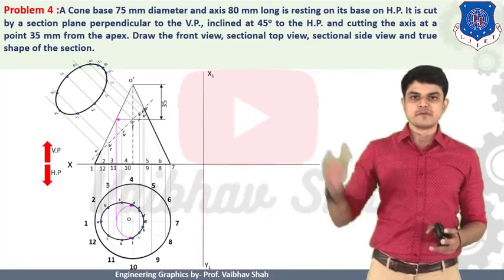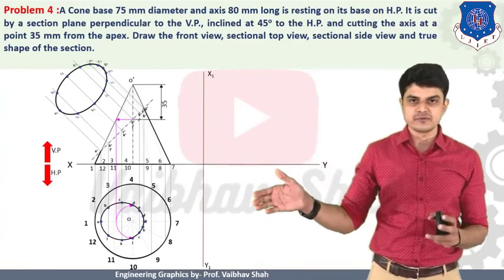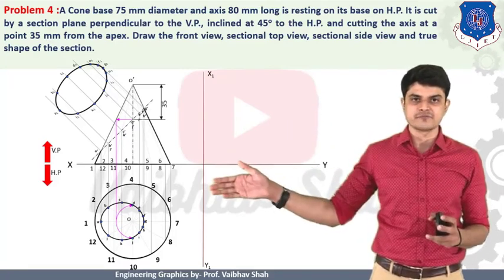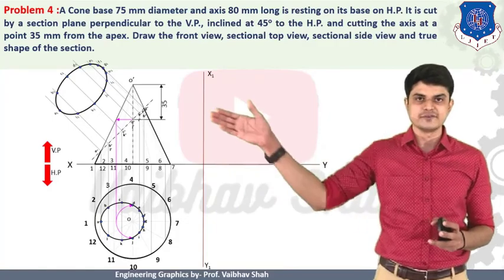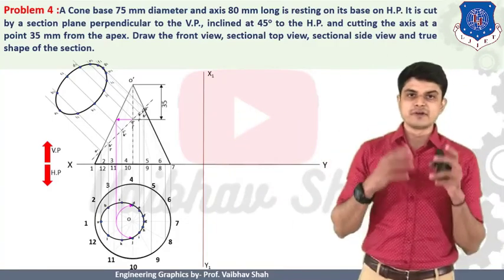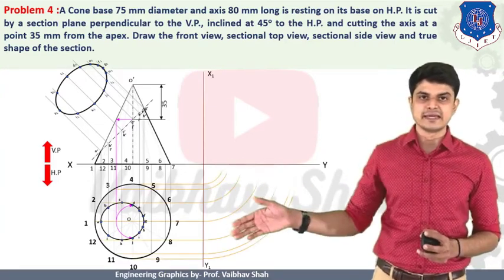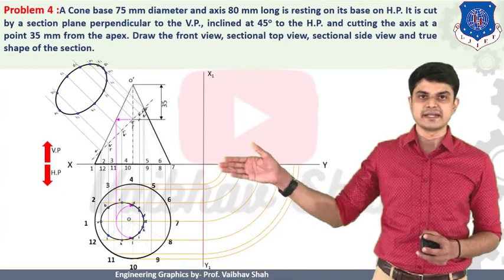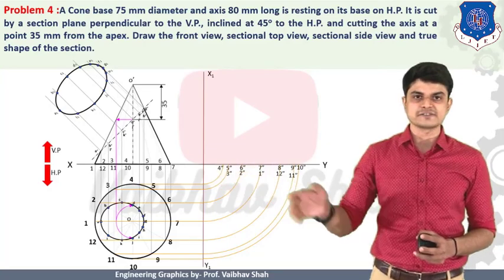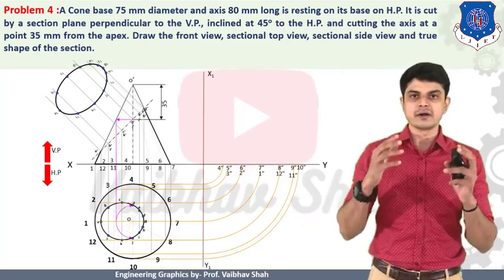Then you should draw the vertical line in order to get your side view. So this is your vertical line x1, y1, and on the right hand side this will be your profile plane. So let us transfer each and every point from your circle onto the right hand side, and we should be transferring your points horizontally in order to have the side view. So now what we should do? You should transfer each and every point on the right hand side onto your x1, y1 line, and you should be transferring each and every point by taking your radius from the center point. So you will be having each of the points transferred onto your x1 y1 line on the right hand side, onto your profile plane or in the side.